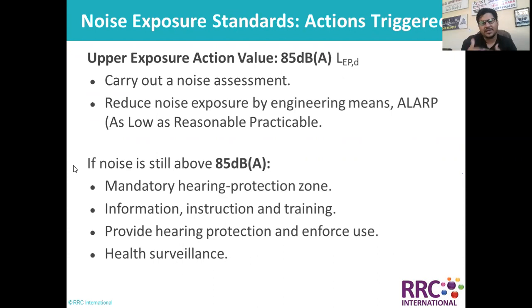That means we have to bring the impact below 85 decibel. That is the challenge if we totally want to rely on the PPEs. If we have a chance to put some more engineering controls, or we use some reliability engineers, they're going to suggest some of the better controls to minimize the noise level. That would be a better option, because PPEs, of course, are the last option. Other than PPEs, we have no other choice. Then definitely we have to provide them.